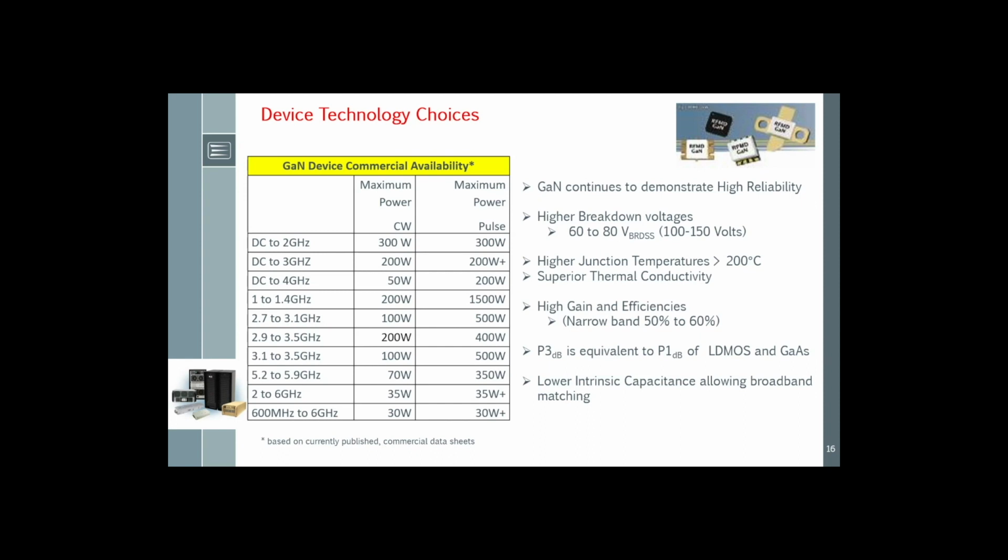It's not the power dissipation. Power dissipation takes microseconds to burn a device, so VSWR sensors can in general be good enough to protect devices. With voltage breakdown, the device is blown in hundreds of nanoseconds, so you need to act much, much faster.